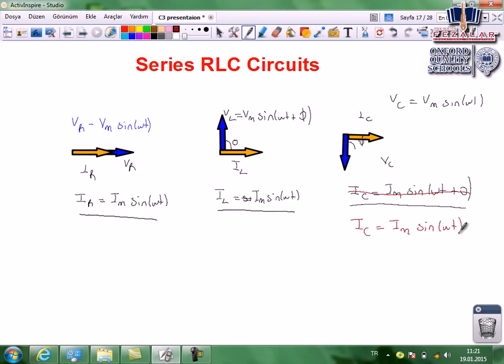But we know in a circuit that contains a pure capacitor, current leads voltage. Initially, current has greater phi, or we can say voltage has smaller phi. So we will change this one, meaning VC equals Vm sine omega t minus phi, we'll write here. Anyway, current leads voltage. Now I want to draw the phasor diagram of voltage.